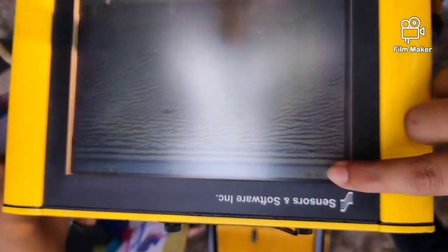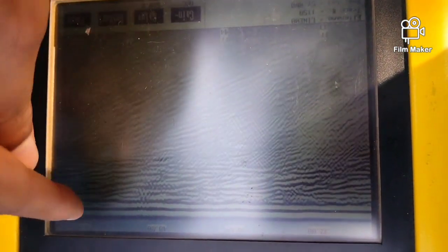This is 6 to 7 meters of depth. This first one is noise. That's the direct wave, because the transmitter is sending down the pulse, but some of the frequency comes directly from the transmitter to the receiver. So it's not going in the ground, just coming from transmitter to receiver. That's why you're getting very, very strong reflectance. Yeah, that's why it's just flat.